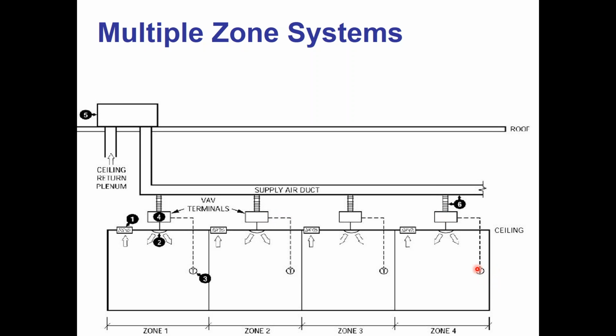There's no such thing as heating right now. We're talking about just cooling. The thermostats can decide how much cooling they want. So for example, if the thermostat is set for, let's say, 73 degrees cooling, and it's 75 degrees in this space down here on the right, that guy wants cooling. He will send a signal to the damper saying, I want more of that cold air that you have available, right? I have this cold 55-degree air, give me some more of that.